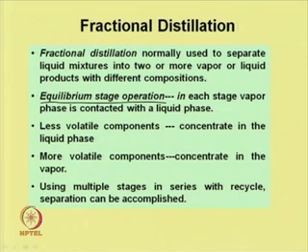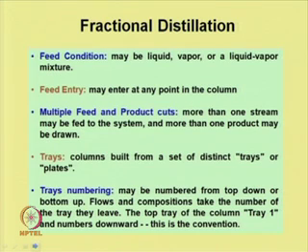So, using multiple stages in series and with recycle or reflux, the separation can be achieved to any degree required. The feed which we use has certain conditions. It may be liquid feed, it may be vapor feed, or it may be a mixture of vapor and liquid.